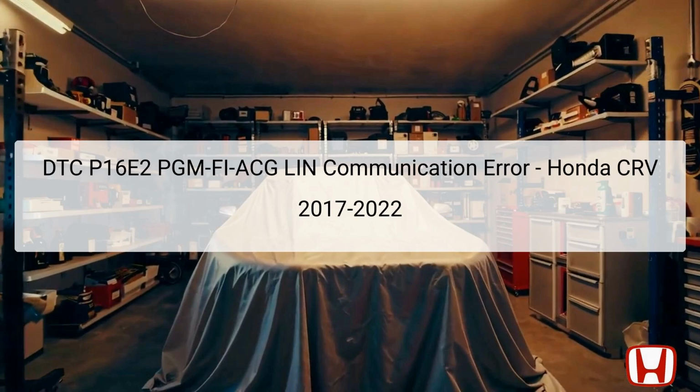This presentation is focused on DTC P16E2, which signifies a PGM-FI-ACG LIN communication error for Honda CRV models from 2017 to 2022. DTC stands for Diagnostic Trouble Code, which is employed by the vehicle's onboard diagnostic system to identify faults in its operations. The code suggests communication issues within the LIN, or local interconnect network, which is crucial for controlling various components such as the alternator and battery sensors.